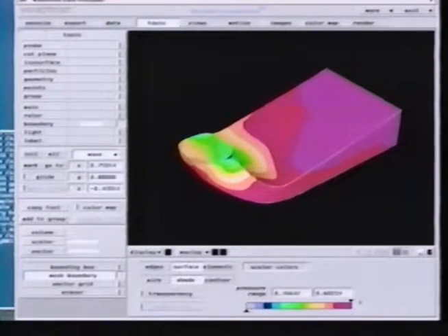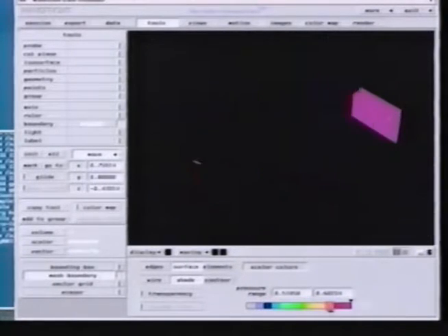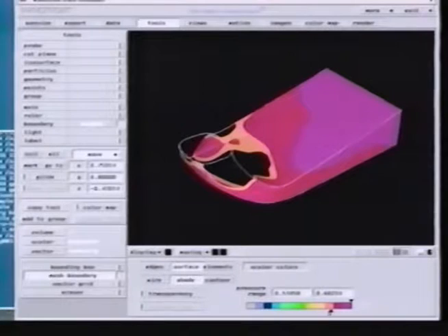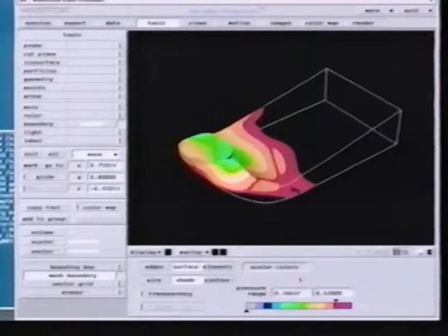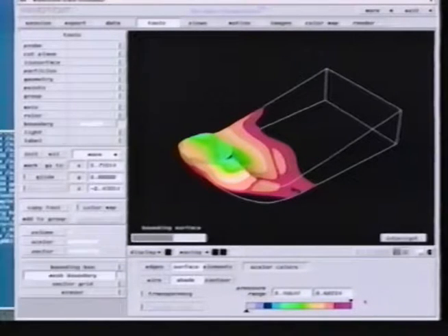The mesh boundary surface display can also be controlled according to data range. By using this color slider, we can input threshold values which determine minimum and maximum data ranges for which the computational grid surface will be calculated and displayed. The color range in the slider is controlled by the Data Visualizer's Color Map Editor. We'll discuss its function a bit later on.